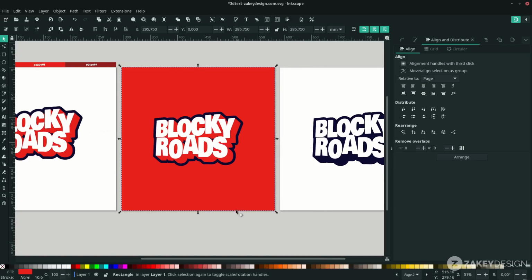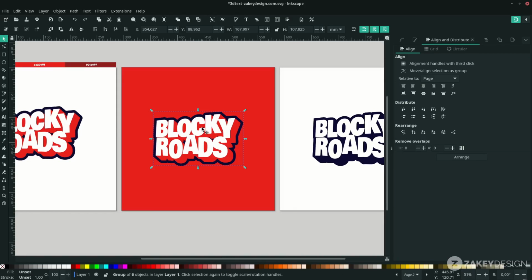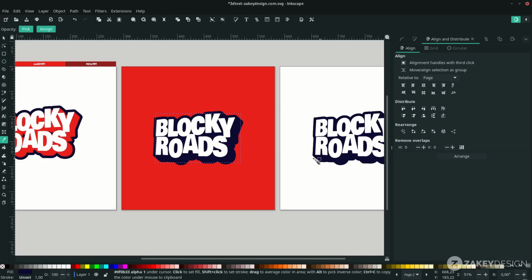Okay. For this red extrude color, I want to change to this color. Oops, I forgot to ungroup it. Ungroup it first, right click, choose ungroup. And select this interpolate effect. Press T, change color to this color.